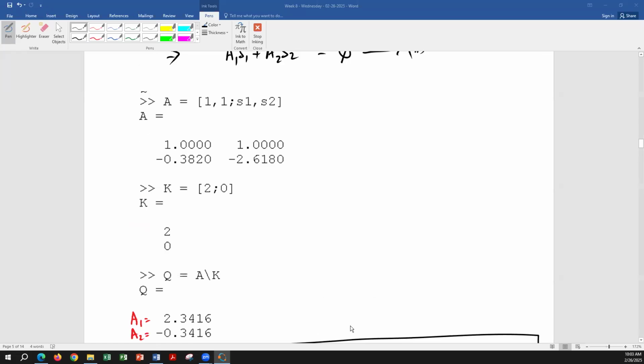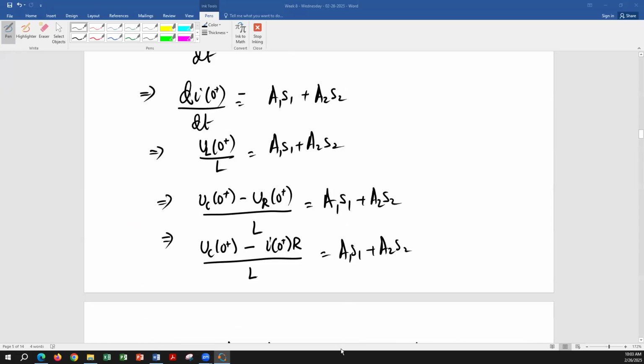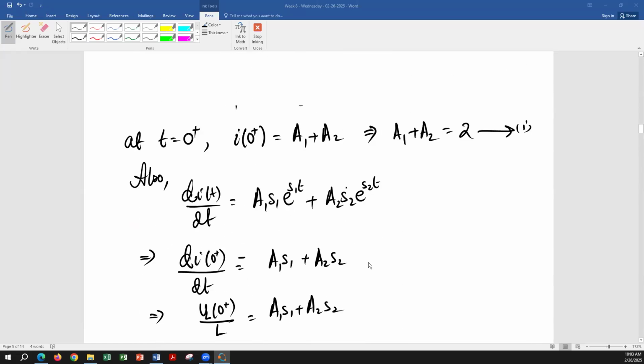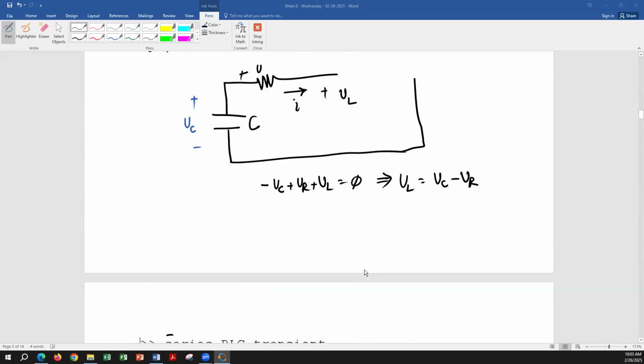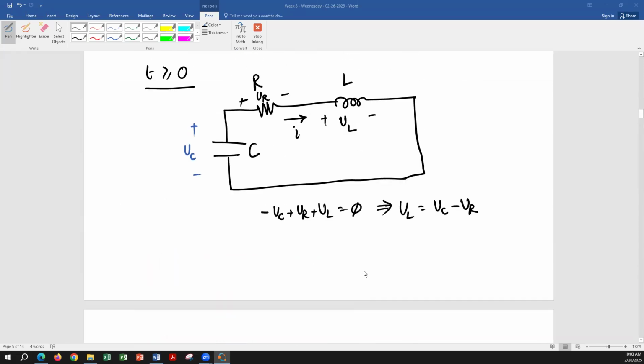Question. How are we going to find now the voltage expression across the inductor, VL(t)? How are we going to find that? Take the derivative of what? V is equal to L di/dt. That's one way to do it. Then there's another way to do it, what is that? It is that equation. But I think that taking the derivative is easier,